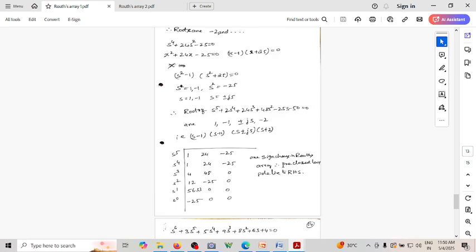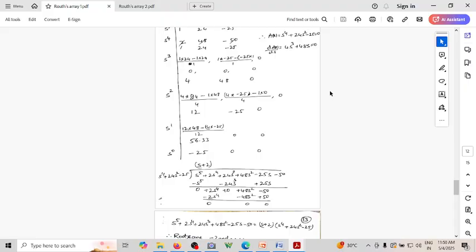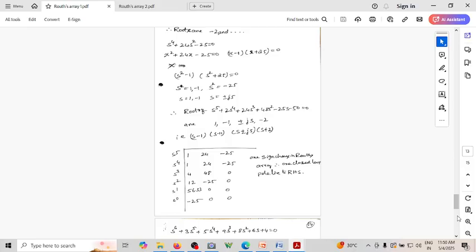How about the exact location? Because we completed this roots array by taking the auxiliary equation. So we actually know the auxiliary equation. We know the second auxiliary equation also. Then we could know the exact pole position, and exact pole positions confirm that there is one pole to the right hand side of the plane, two are onto the left hand side, and two are on the imaginary axis. So that's the conclusion of this particular problem. So this is a very interesting problem. I recommend you to understand it to the core and then proceed.